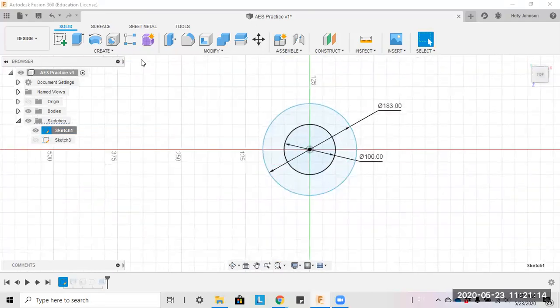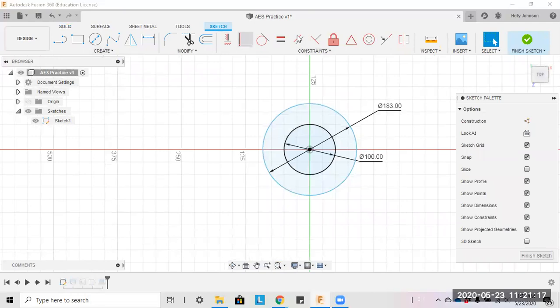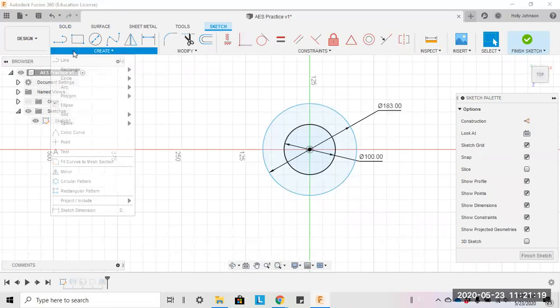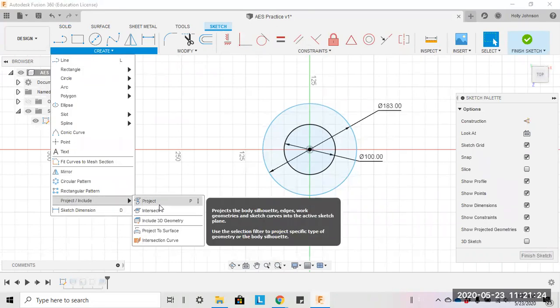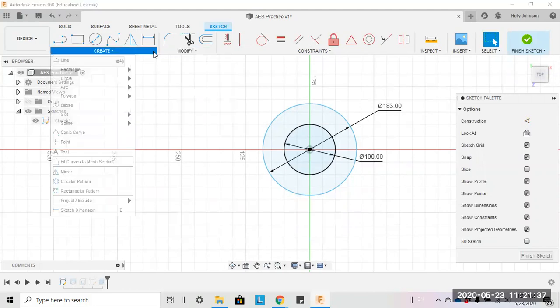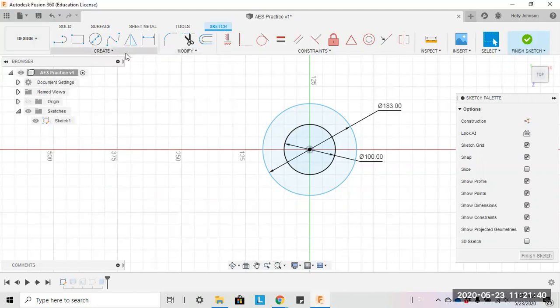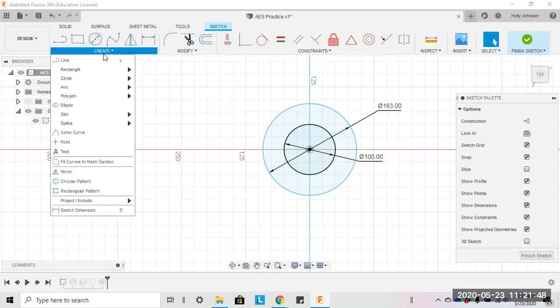here we go. If you remember within the sketch, you have this project include section. What I've seen, at least on SolidWorks, I can't speak for all softwares, is that you're generally going to have it be called convert entities. It will probably appear less drop-downy like this. You can usually right click on these and it has a drop-down folder of some sort for the different definitions of a circle, versus having to click the drop-down to get it each time.